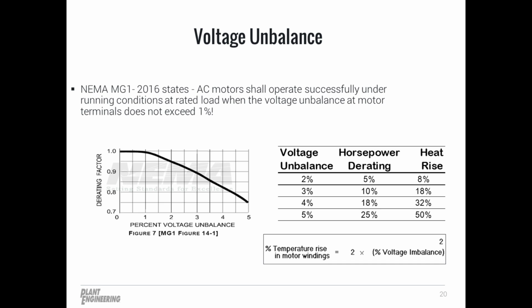Continuing to look at voltage, imbalance is another major problem. We've had quite a few metering and verification projects over the years, and we've seen large amounts of voltage imbalance at field facilities, just like yours. We do work with the utilities very often, and the utility will typically have a power purchase agreement in place with your facility, and it will set a limit on the amount of voltage imbalance that would be coming from the grid side.